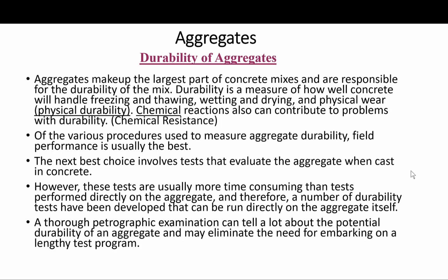Of the various procedures used to measure aggregate durability, basically field performance is the best. The next best choice involves tests that evaluate the aggregates when cast in concrete. But these tests are usually more time consuming than tests performed directly on the aggregates. And therefore, a number of durability tests have been developed that can be run directly on the aggregate itself, just for convenience and for the sake of time.